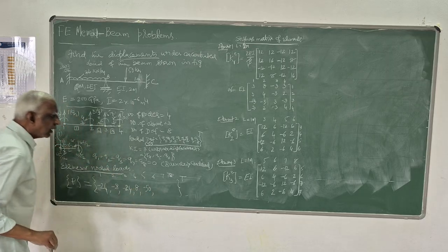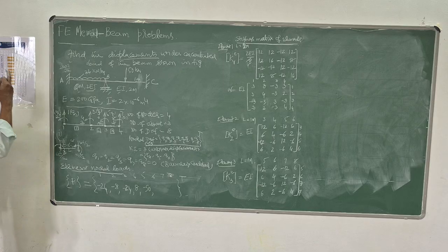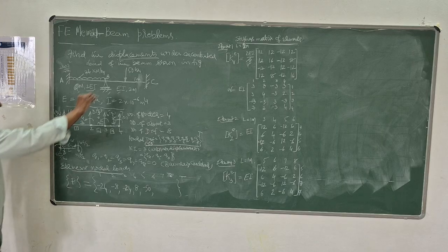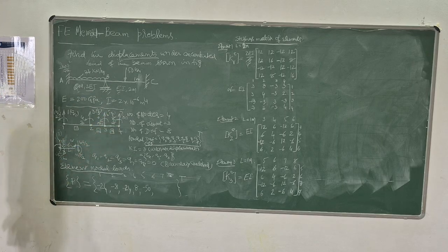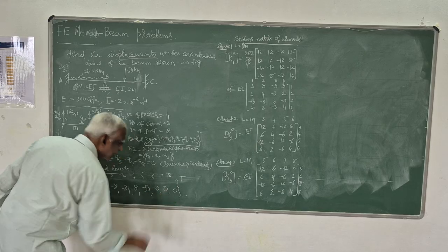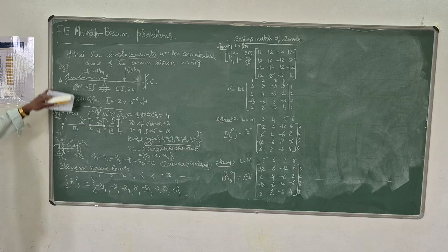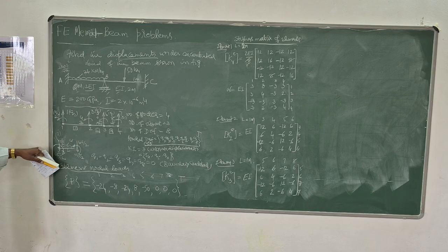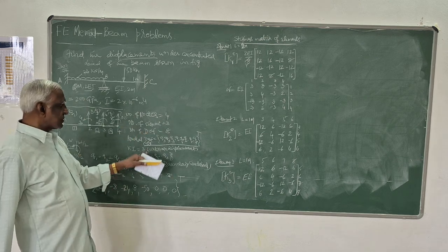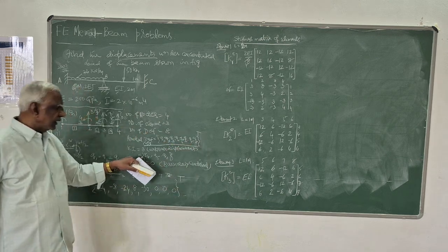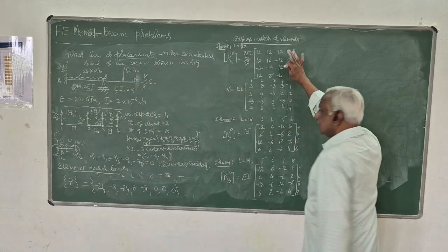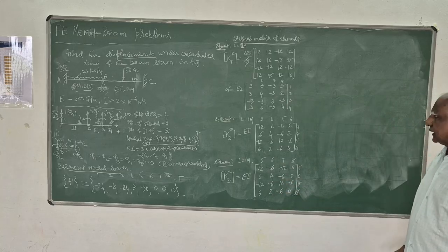That you have to remember, all concentrated loads acting up positive, and all moments in the anti-clockwise direction positive. If clockwise moment is given, you take it as moment, negative. And 6, no load, 7, no load, 8, load. This also is a formula in the beginning itself, first step. Then we have nodal load vector, nodal degrees of freedom, and what are the unknown degrees of freedom, and element stiffness matrix. This much you have generated.